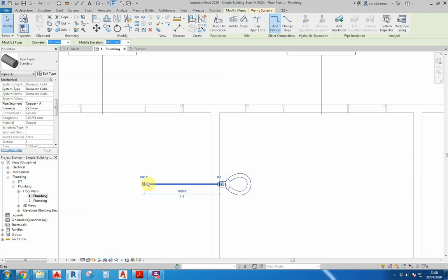The controls that you see at the end of the item that you've got selected enable you to drag, or not in this case but in other cases, to flip, lock and rotate the elements. They're usually associated with fittings where you can change the direction or angle of the fitting. These also have connectors, so it's controls and connectors at the end of these items, and the connectors control how related elements attach to one another with intelligence about size, needed fittings and system information, and this only applies in the